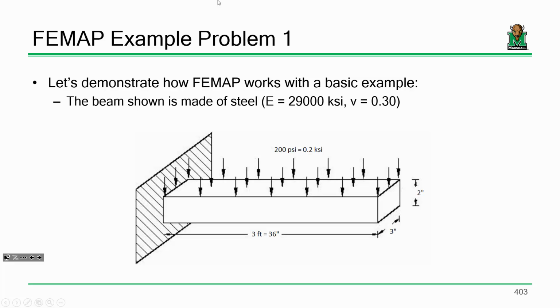Okay? Now, I'm going through all of this because I'm going to make a statement right now that's going to surprise you. Let me ask you a question: what units do you think FEMAP uses? What unit system? Just guess, anybody. The answer is FEMAP does not use a unit system at all. In fact, many large-scale finite element packages do not employ a specific unit system. The idea is you're the analyst. You use whatever units you want, okay? You just have to keep track of it.